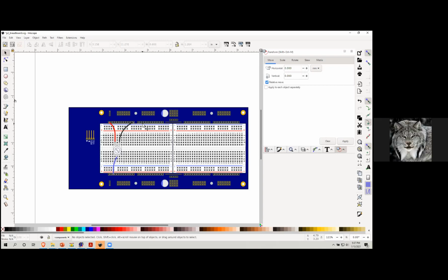Yeah, I agree with you there on that last statement about the P2 versus P1. I'm finding the P2 a lot easier to code, just because the instruction set is so much more powerful, and you can find an instruction to do something that you'd normally have to write a whole function to do. I'm finding that all the time. You're replacing several lines, especially in the assembly. I think I told this story the other day. In my RGB pixel driver for the P1, there's about 8 or 9 lines of code to swap a couple of bytes inside a given long. That takes one line in the P2. It's amazing.